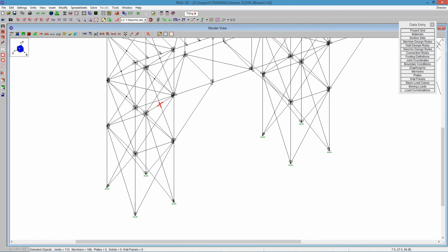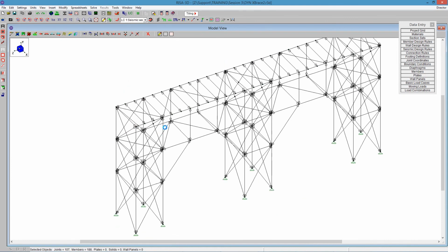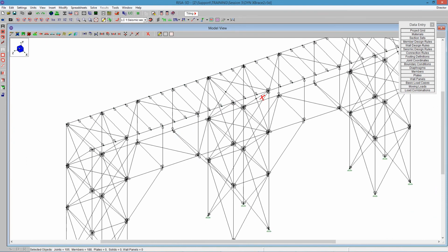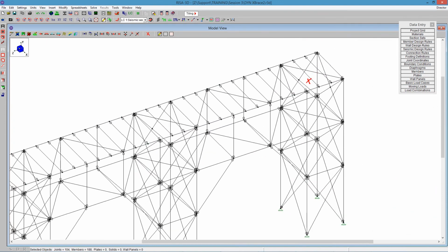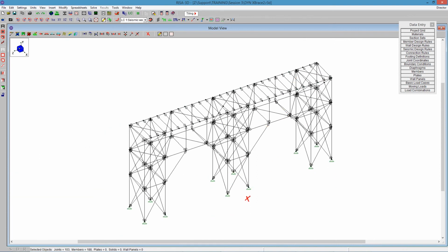So just a couple more, and pretty easy. One of the things too is why did we have nodes there? It's a typical modeling thing where people just do a model merge and it can create nodes for you. There are options so that you don't create those nodes, and it's a good thing to not create those nodes, even if you're doing a static analysis.